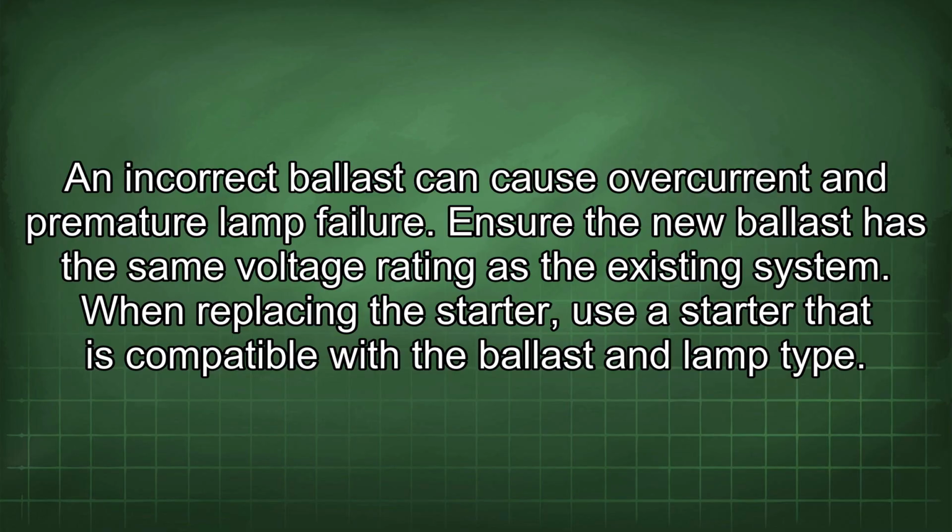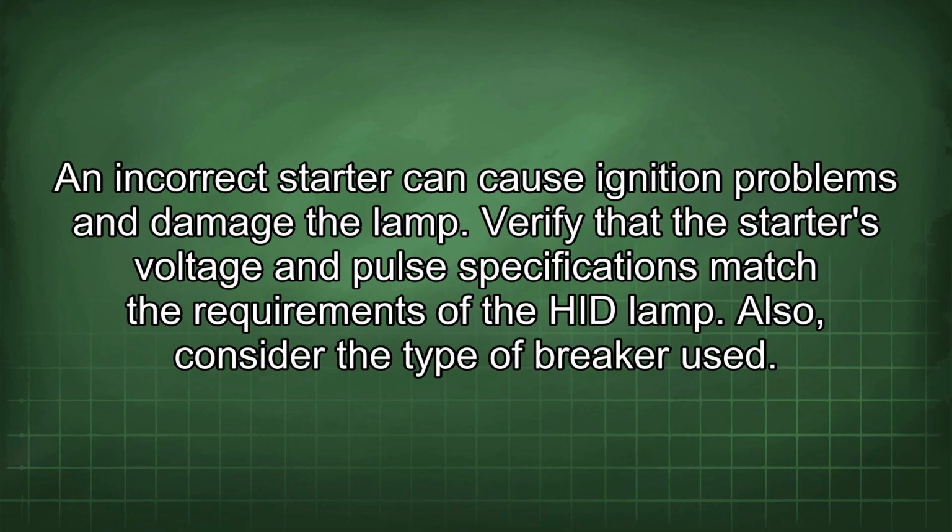When replacing the starter, use a starter that is compatible with the ballast and lamp type. An incorrect starter can cause ignition problems and damage the lamp. Verify that the starter's voltage and pulse specifications match the requirements of the HID lamp.